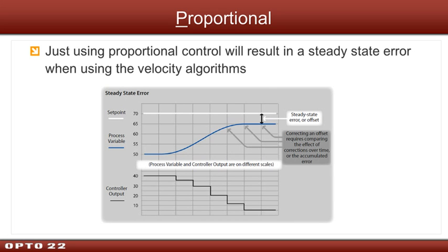We're not going to see a change. So proportional control on its own is not very popular, and it had its use way back, but this very problem of not having the process variable meet the set point was the downfall for the proportional only control.